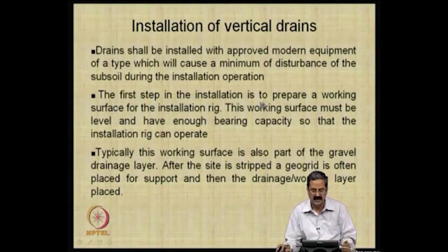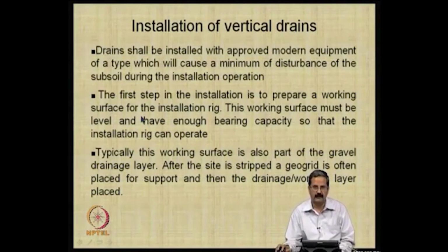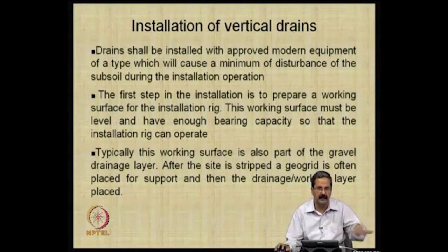The first step in the installation is to prepare a working surface for the installation rig, like you are bringing a big rig there, and the working surface must be level and have enough bearing capacity so that the installation rig can operate. In fact, you may not believe, there are cases where the installation rig can sink in. If the soil is so poor, definitely you can't bring it in. So, you may have to create a temporary platform for it.